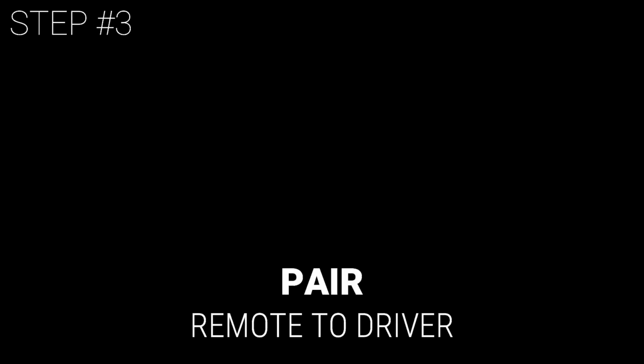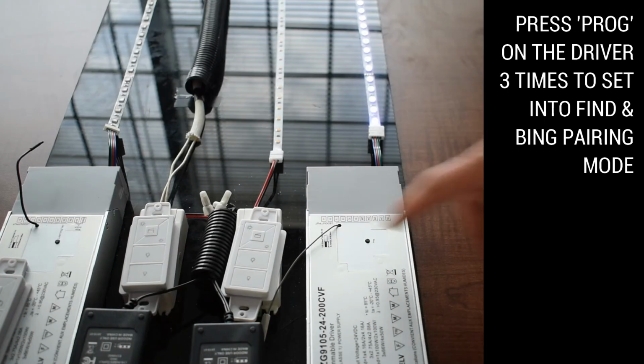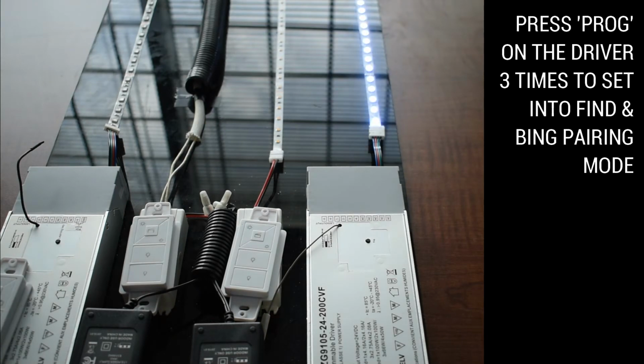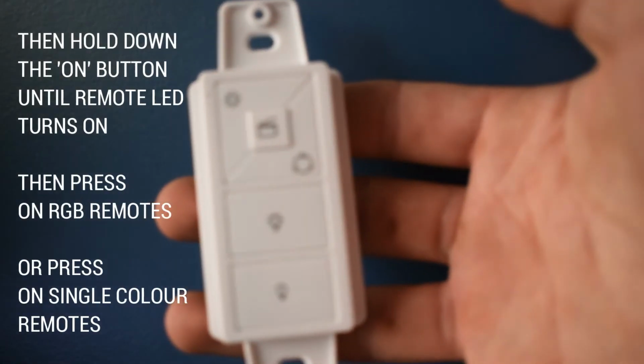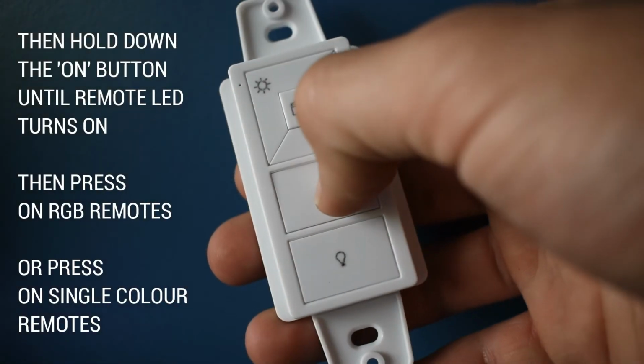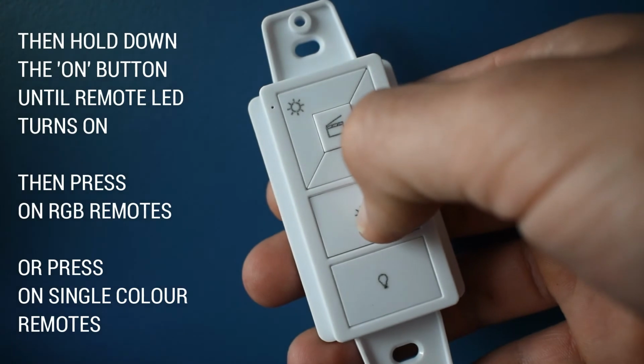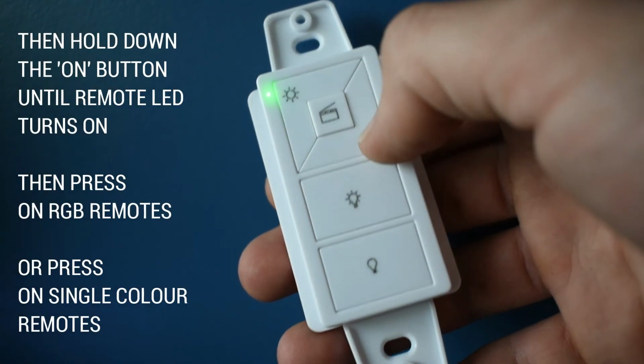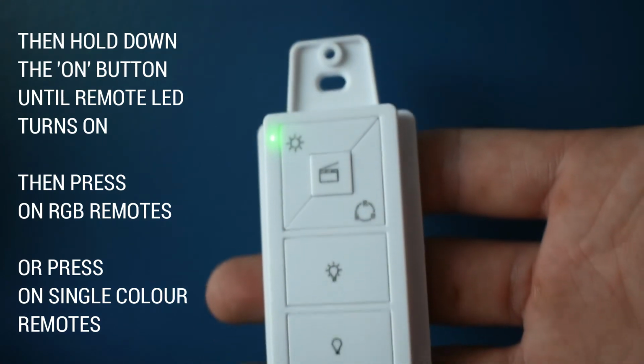The last step here is to pair the remote to the driver. Set the driver into Find and Bind pairing mode by pressing the program button 3 times. Then, set the Zigbee wall button remote into Find and Bind mode. Do this by holding down the on button until the remote LED turns on. Then, press either the RGB button or the brightness down button, depending on the remote type.